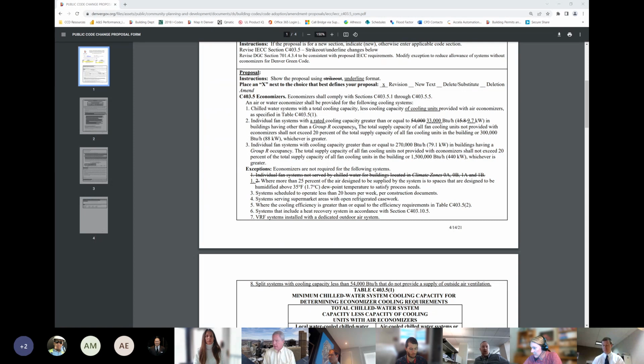You still have the 54,000 cutoff there. I don't think exception 8 would allow you to have a 100,000 BTUH system without an economizer. It does say with less than 54,000 BTUH. So I guess I'm missing the point then, because aren't we already limited to individual fan cooling units less than 54,000? The whole proposal is changing the 54,000 to 33,000. So my point is that split systems between 33 and 54,000 BTUH are...